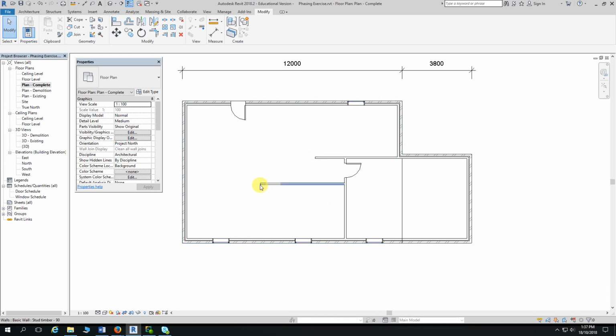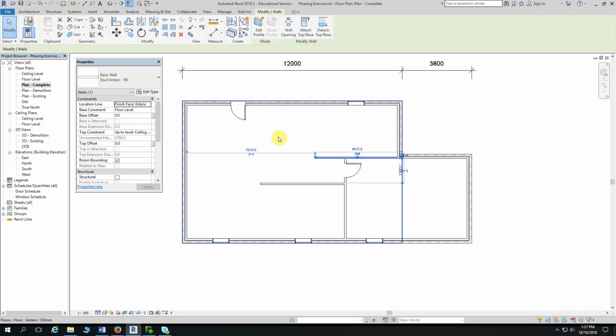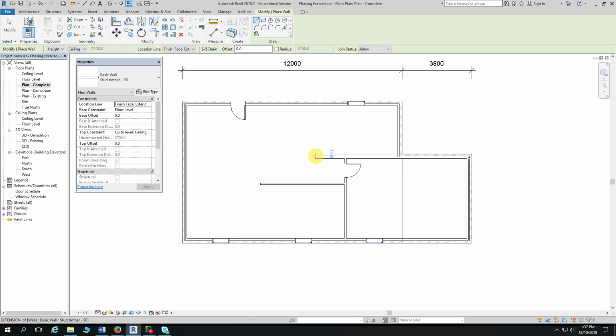And we're going to add a new wall section from the end of this wall over to the exterior wall on the left. So again, we select the existing wall, do a create similar, and then all being well, if you connect to this one and draw upwards, it should work as expected.